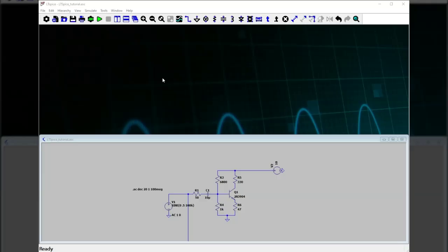So I set a total simulation time of 1 millisecond. That would be 100 cycles. And then told LTspice to start saving data at 0.9 of a millisecond. So basically, I didn't need to enter that second input, but this will just save me magnifying the response to avoid having a bunch of cycles all crammed together real close.